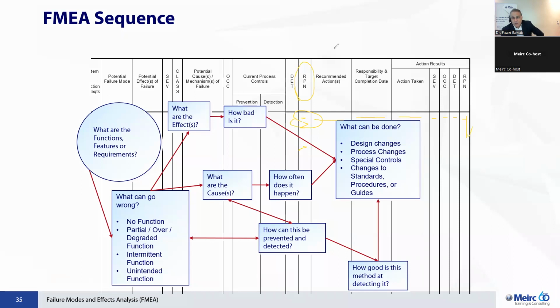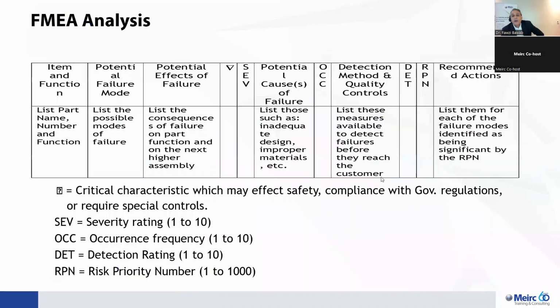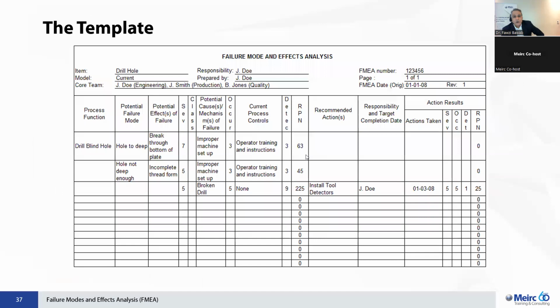which is the same function. So if you think here of an example, so here is again just the template of the FMEA function, potential, severity, occurrence, and then you'll need to fill here the numbers to look something like this. So here's an example where you can immediately see that here is the name of the function, here is the potential failure, here is the consequence of the failure, because this is what we're trying to evaluate. And then you can see the team has agreed that they have put 7 here, they have put 3 here, they have put 3 here.